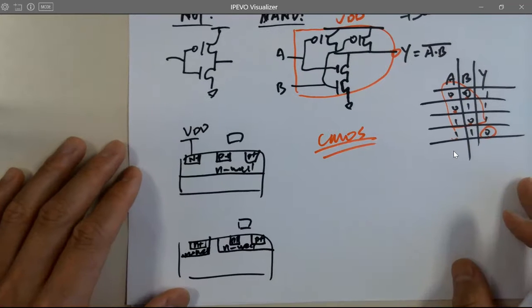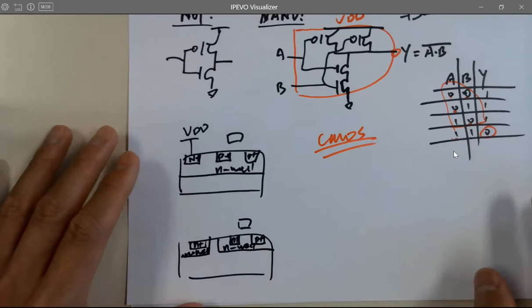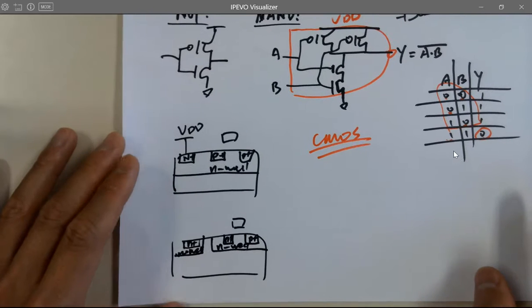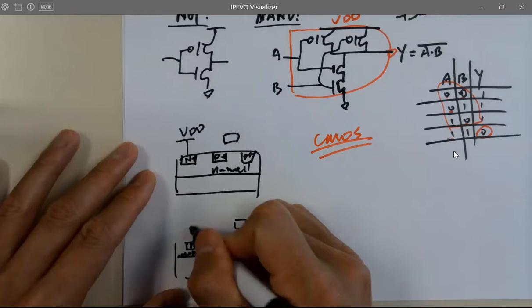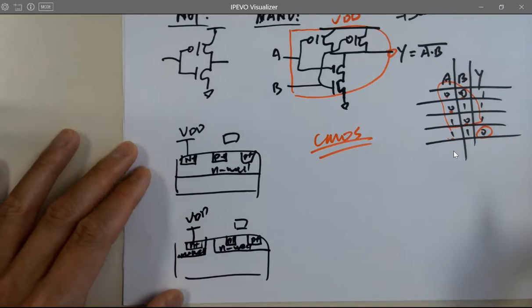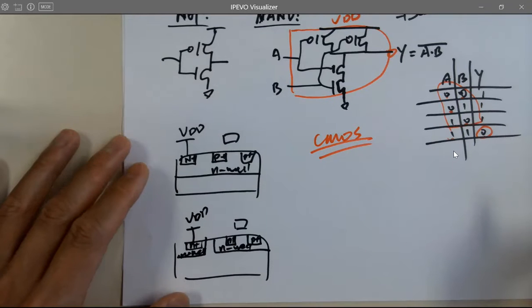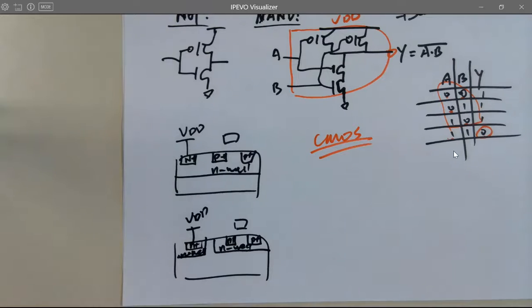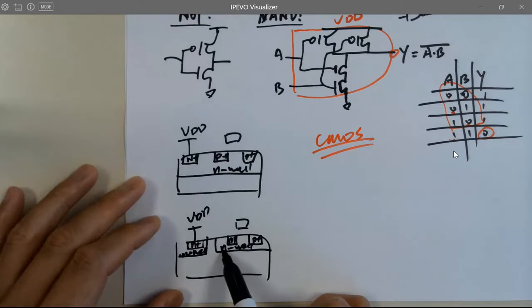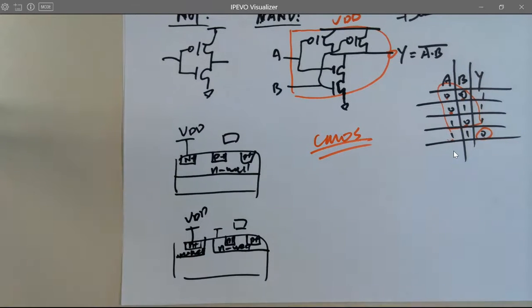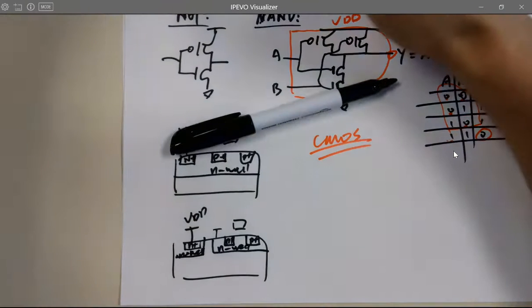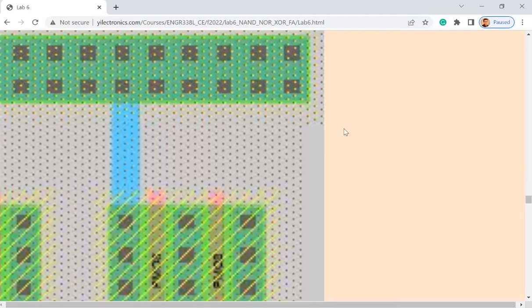So you are separating the two N wells. And are we going to get an error or not? Because this one is short to VDD, right? If you separate them, what's going to happen? It's not body effect. It's called latch up. Yeah, it's not even connected. So your N well here is not shorted to the highest potential of the circuit, which is the problem. So sometimes you want to pay attention to it. If you move this up, there's no overlap between these two N wells, then you are getting a problem.